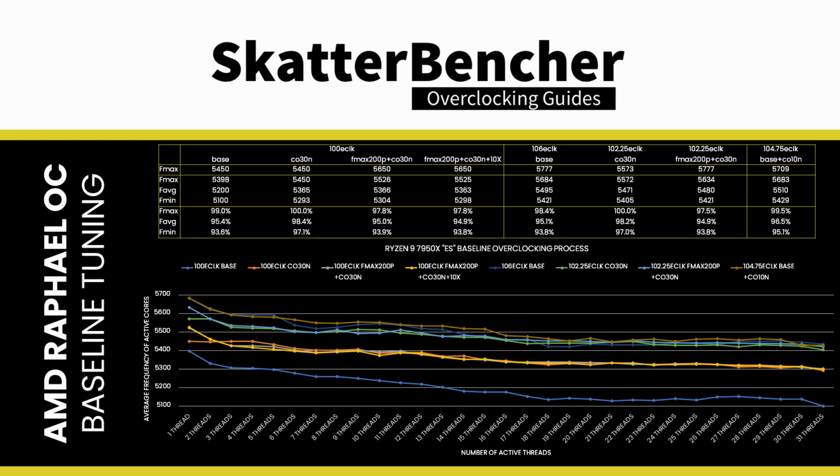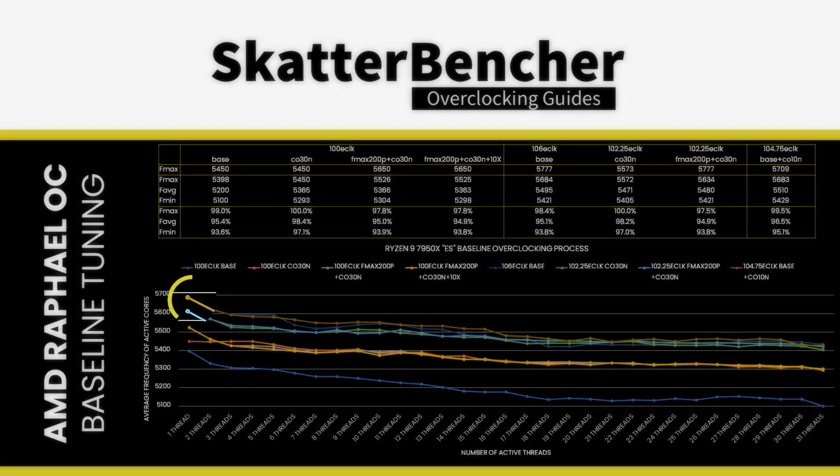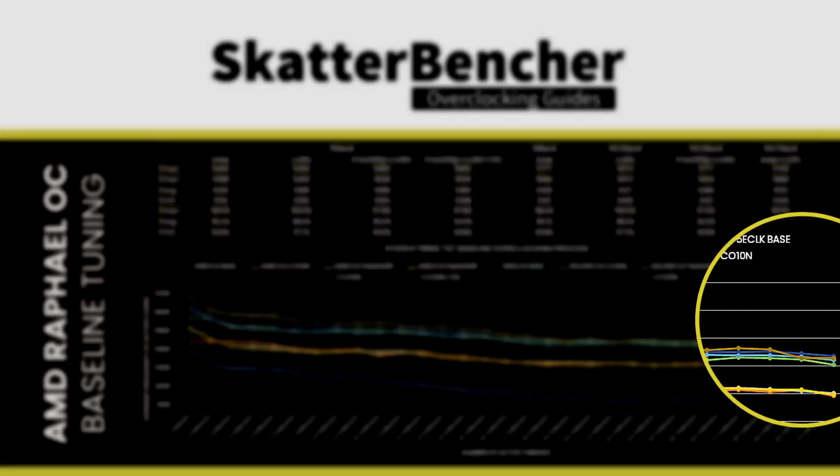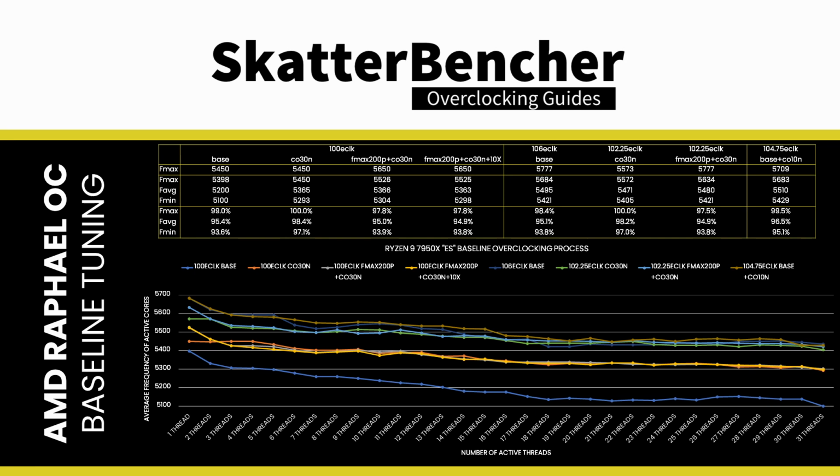The sweet spot case frequency ranges from 5688 MHz at one active thread to 5430 MHz with 31 active threads. The programmed Fmax is 5736 MHz, which means our effective Fmax is at 99.2%. The average frequency is 5500 MHz, plus 300 over base, and the minimum frequency is 5430 MHz, plus 330 MHz over base.